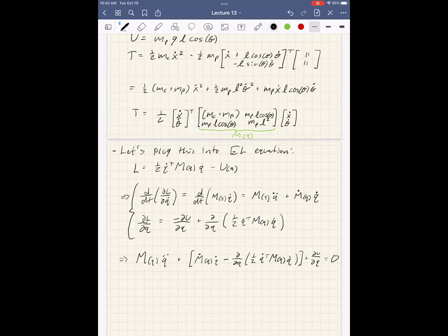The stuff in the middle all has to do with derivatives of m, right? And it turns out these two terms look pretty similar. If I chain rule this guy, I get a dm dq in here, and this guy has some dm dq too, times q dot. So both of them involve a dm dq times a q dot squared-ish thing. The reason I didn't write these out in more detail is that they both end up being third-rank tensor terms, and it just gets messy.